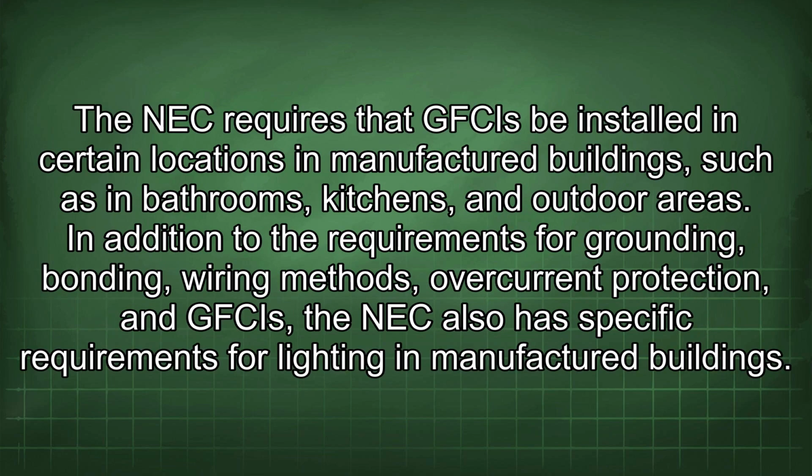The NEC requires that GFCIs be installed in certain locations in manufactured buildings, such as in bathrooms, kitchens, and outdoor areas.